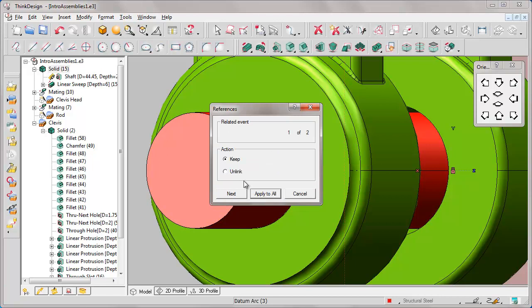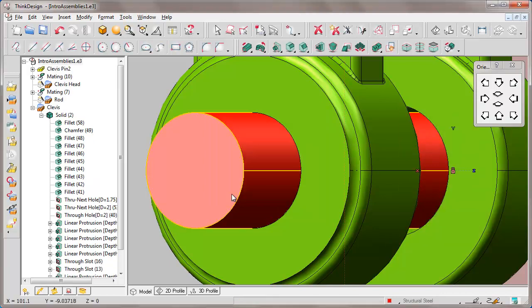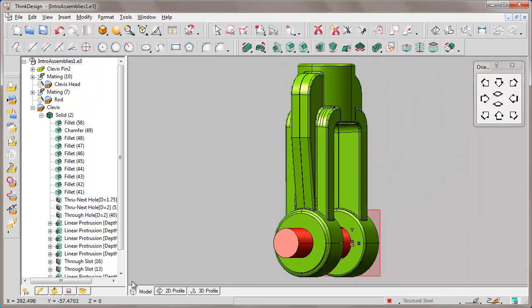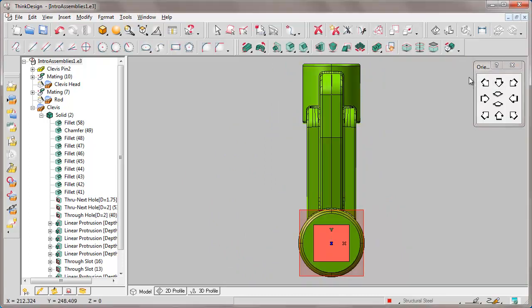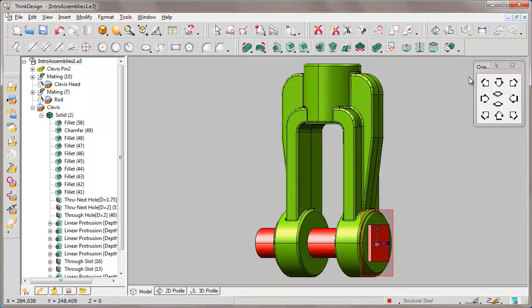Upon saving, we are asked what to do with references because we created the first solid laying the work plane on the Clevice face and the pin laid on the face of the first solid with links between the new object and Clevice that we can keep, not being able to use the part in other assemblies, or break, possibly using it in other assemblies once made as an external reference.